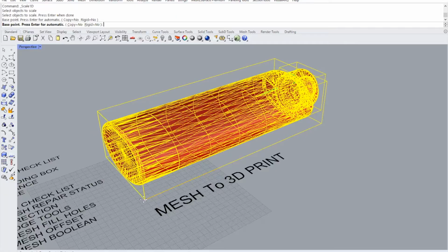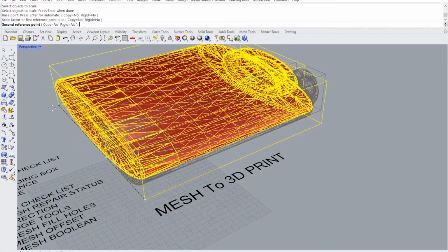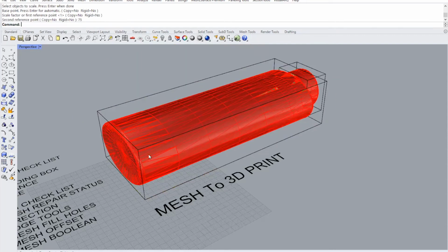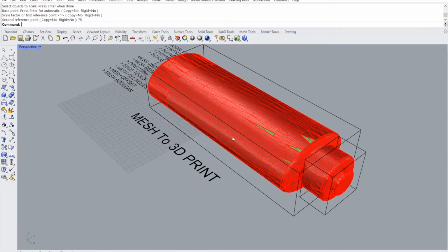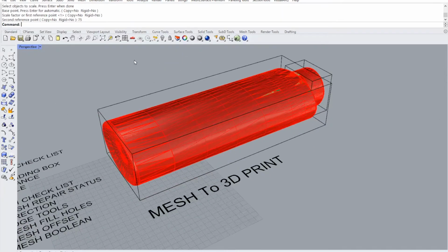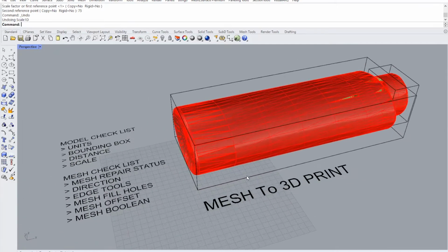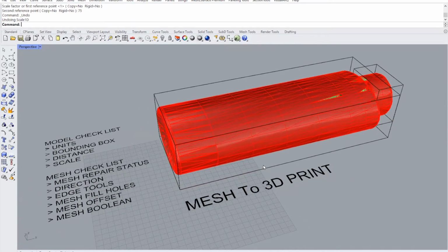In terms of length, this to this, stretch this. That's one directional, and I type in 75. My only concern would be the roundness here, but I just demonstrated the 1D direction for you. I will just undo this and keep the default one. So we're done with the distance. We finished the scale. So this model now is prepared for mesh checking in the next section.